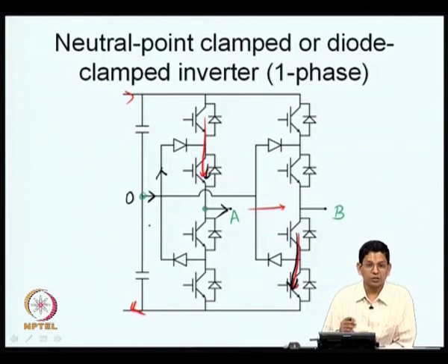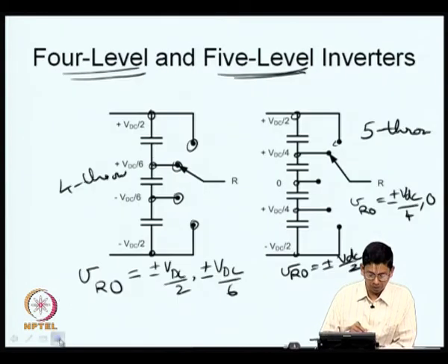The advantage of a 3-level converter itself lies in the fact that it gives you better waveform quality, that is, you are able to connect the pole to the midpoint. That also provides a disadvantage, namely the DC bus balance could be lost. You need good modulation and control methods to deal with that. So that is something we will look at when we are doing modulation of the DC bus.